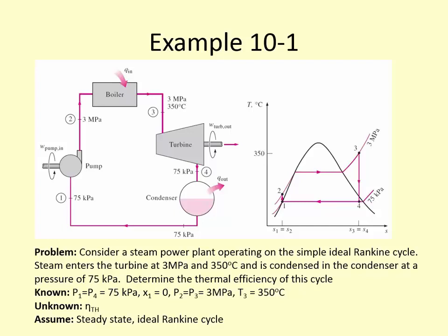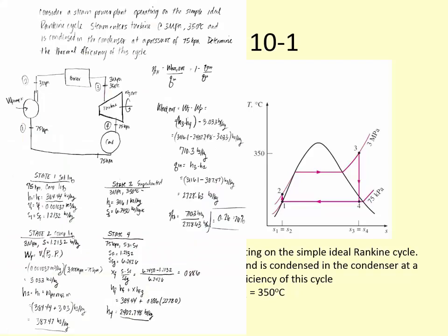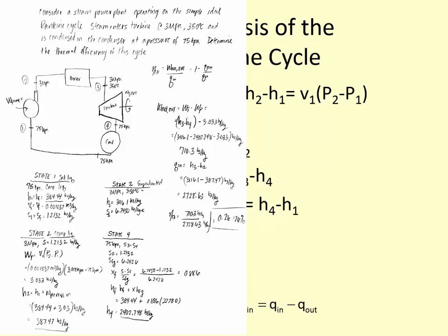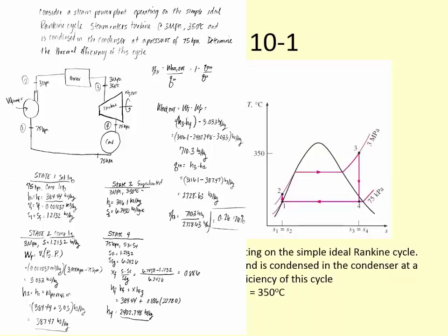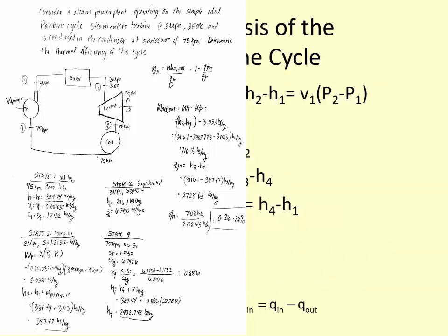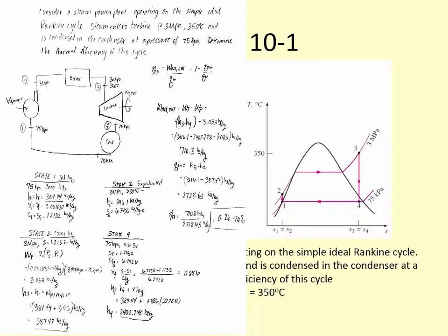Let's first find, let's say, the pump work in. So pump work will occur from state 1 to state 2. So let's look up some properties at state 1 and state 2. And what is the equation for pump work in? From the previous slide, we can use the enthalpies or, yeah, V1 times P2 minus P1. Specific volume. In that case, because it's lowercase w, it would have to be a lowercase v. If it was uppercase W, then it would have to be uppercase V, total volume.